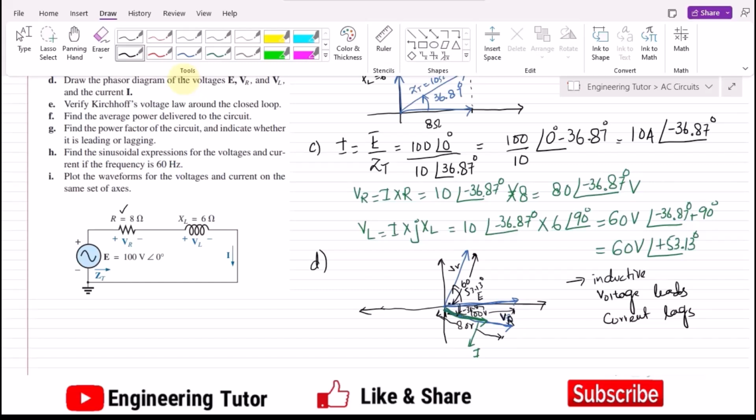Similarly, we will also find the value of the power factor. As the current is lagging here, the power factor will also lag. Because the power factor of any circuit is related to the current. Whether the current is lagging or leading, the power factor will also be lagging or leading in that circuit. Okay, so that is the phasor diagram of this circuit.